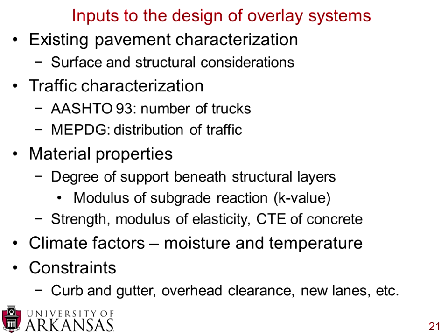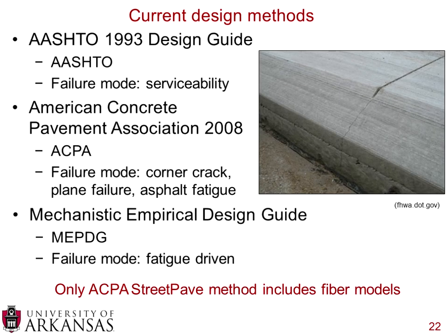A very popular use of these concrete overlays is adding lanes on the side. However, that will start changing geometries, that'll start changing slopes of your road and final grades of your surface. So these are other types of constraints that come into play.